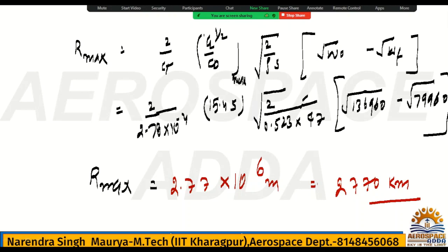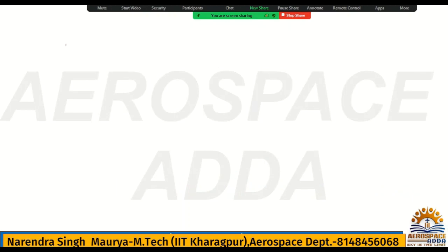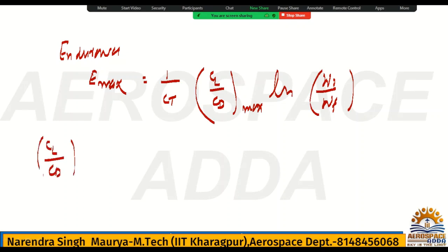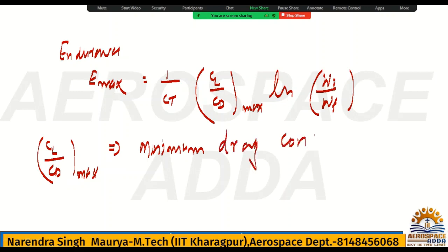Okay. Now we'll go for the endurance. Please calculate endurance. Similarly, endurance maximum you will calculate. Sometimes in a problem they will not tell you whether it is maximum or minimum, but you have to consider. So you need to write 1 upon CT, CL by CD max, ln W naught by W. How to calculate CL by CD max? This CL by CD max is nothing but the minimum drag condition that you must be aware of.